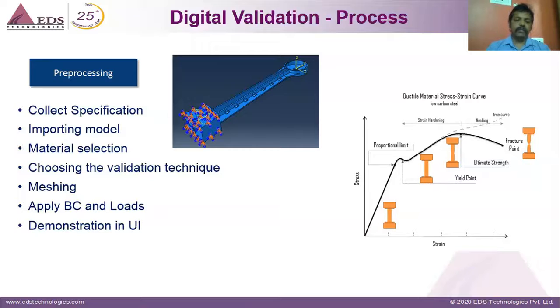Next is meshing, which is very important. Meshing is nothing but the same truss and structure whatever I spoke about in the first two or three slides. The formula remains the same, but today we have more degrees of freedom. Once you do the meshing, there is no connectivity between the 3D model and the analysis. The 3D model is morphed using nodes and elements. Nodes and elements will take the shape of the 3D, and from then there is no relation to the 3D. The 3D model is just an outline for the meshing module, which considers all the boundaries and creates a meshed model consisting of nodes and elements.